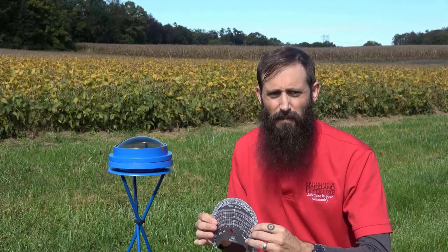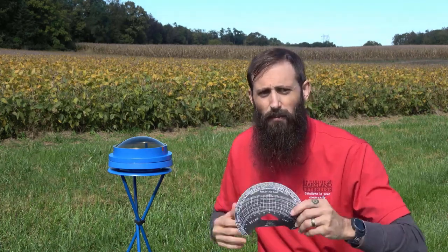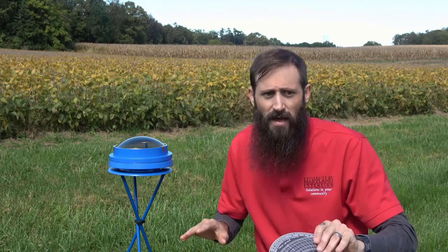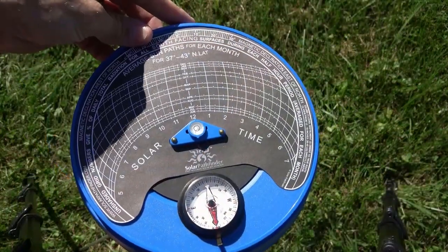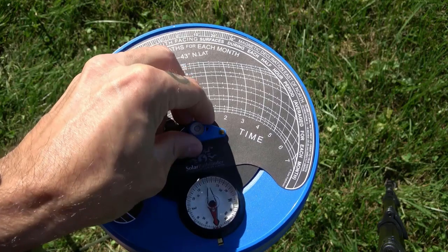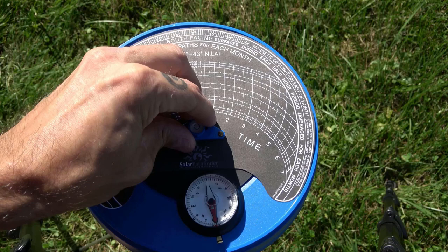Now we'll use this sun path diagram in conjunction with the Solar Pathfinder to predict what percent of the sunlight we can expect at this particular location through every month of the year. This device has to be positioned at the specific location as well as the height that we expect to install the system. We'll start by rotating the unit until the magnetic compass is pointing north. Then we'll adjust for the proper magnetic declination of this location by rotating the diagram until it's facing true south.